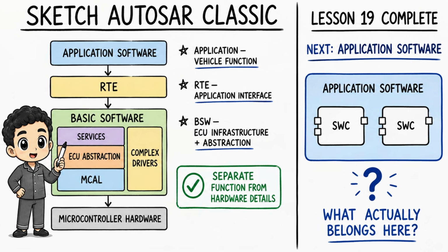The low-power microcontroller control signal then drives suitable external power electronics, and those power electronics supply the fan motor. This is why the layered architecture matters. Without these boundaries, application code becomes entangled with microcontroller details, board layout, communication hardware, memory technology, and project-specific integration choices. A hardware change can then force changes far above the hardware. AUTOSAR doesn't magically eliminate all project work, but the separation supports hardware-independent application development, standardized basic software, software integration from different sources, and reuse across ECU variants when the interfaces and configuration allow it.